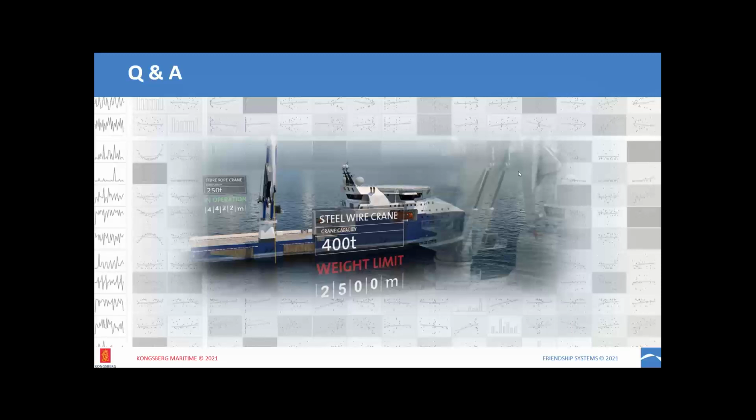Yeah, thanks for the question. We have used it already for other vessels, and as it's still under development, it took more than I wished. But still, it depends a lot on what you're interested in optimizing, right? So if you want to investigate the amount of wing subdivisions or the length of specific tanks, then you don't need to parameterize the whole vessel. You would put design parameters only in the area that you're interested in, and that makes things a little bit faster.